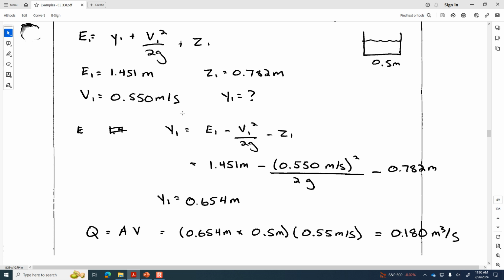We'll come back to this a lot when we are doing the non-uniform flow section because we're going to use this energy approach to find out what happens when we drop obstacles in the channel, like a step that the water has to flow over, or if there are obstructions like a channel contraction, or when the channel gets wider, if water's flowing off of a step, then we can use the energy equation to tell us what's the new depth downstream.